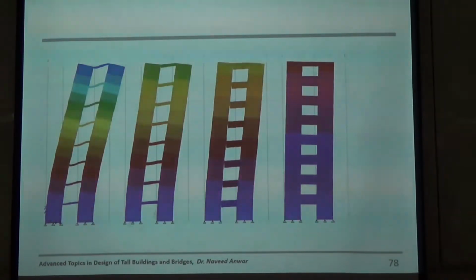And we can also provide hinging to make sure that when there is a strong earthquake, it just has hinging and does not cause failure. Sometimes we design these coupling beams to be replaced. So they can actually be steel beams, they can be replaced if they are damaged.